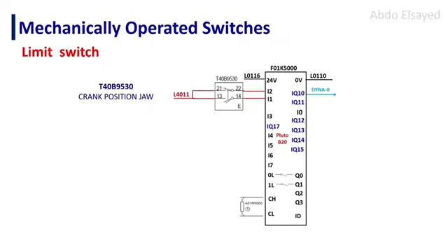An example from Tetra Pak machines is the one used in crank handle sensor, which is connected to the safety circuit. It is connected to 24 volt supply, and the other 2 points are connected to safety PLC. When it is activated, these 2 points should change their feedback to the safety PLC.